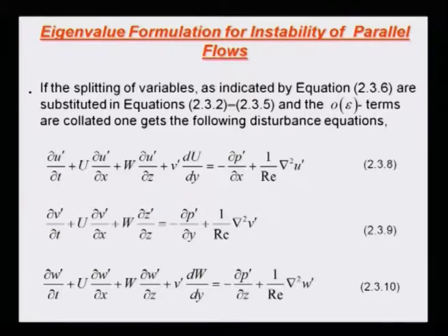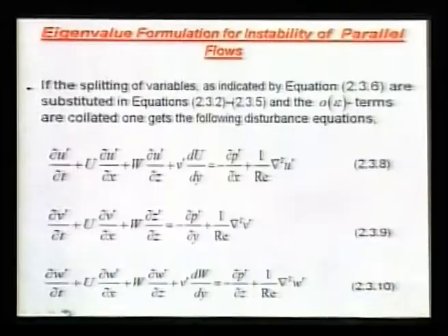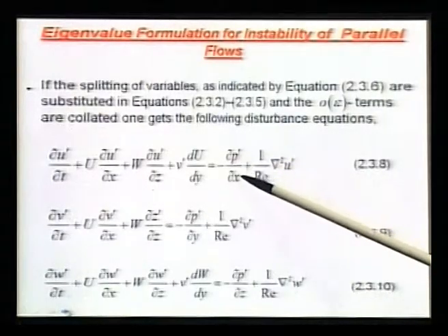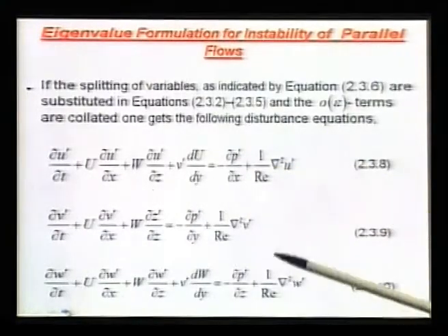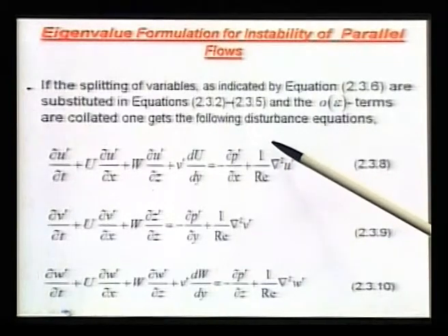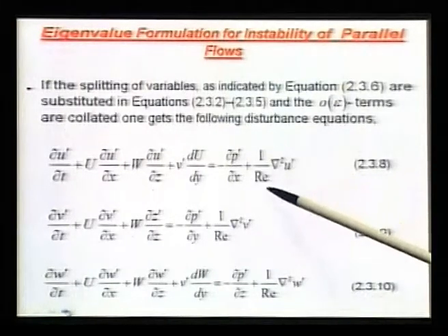Rho times u infinity square. We are focusing our attention on incompressible flow, so rho is a constant. So, I will non-dimensionalize the pressure by rho u infinity square, that is what we are getting here, that del p by del x, rho has disappeared, and you get in front of the diffusion term 1 over Re.